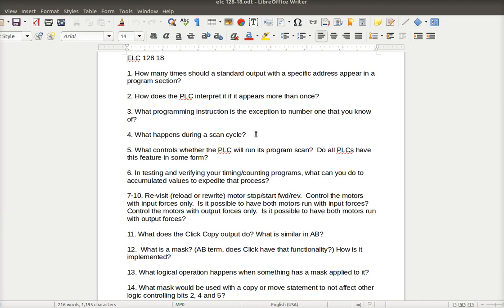And then there's a force table for outputs where you can actually force an output either on or off and disregard the logic. So once you apply the output forces, then you would update the actual outputs. So there's actually two more parts to a typical PLC scan cycle, and that's when you deal with the forces.